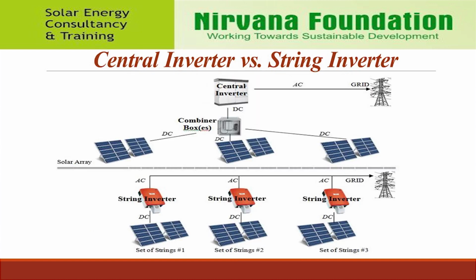Central inverters centralize the plant's power into one place, while string combiners connect wires from each row of panels together, then recombiners combine the output of the string combiners together to feed into the central inverter. Central inverter units are physically much larger than string inverters, use longer wires and can convert more power per unit. Central inverters are less expensive than string overall for large utility scale installations because fewer are required per site. But for smaller utility scale projects, string inverters could win out for their easier serviceability.